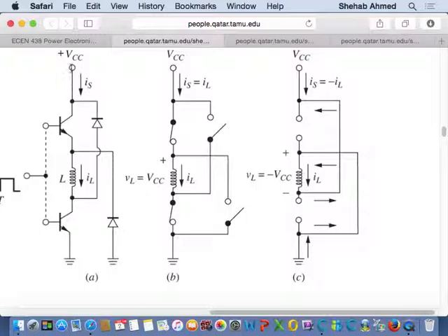And wow, it's connected to the source. That's fine. But for me to push current back into the source, I have to have a closed loop, right? So I've added this diode as well. Current will flow out of the inductor, forward bias this diode, through the source, and now I flip the polarity of current through the source. What does that mean I'm doing to the source? I'm charging it, right? The passive sign notation we talked about always assumed that sources have a positive voltage and current is coming out of the positive terminal. If I flip the current polarity, I'm charging the source, right?